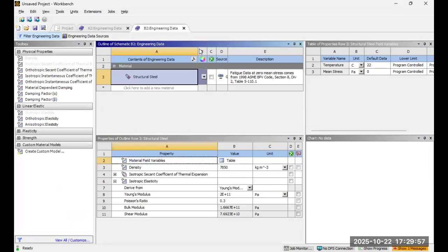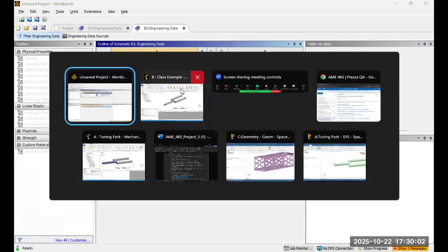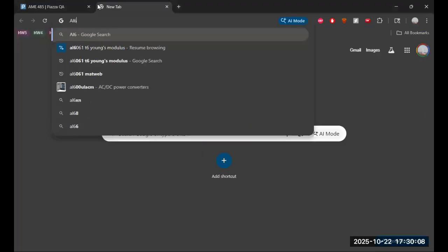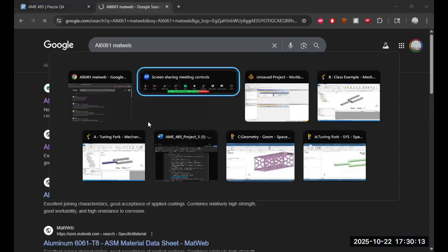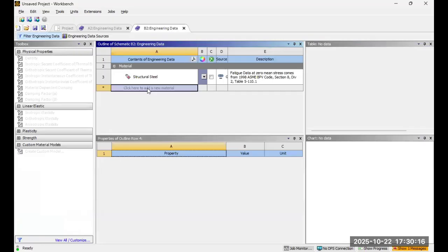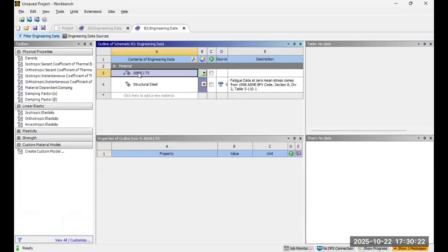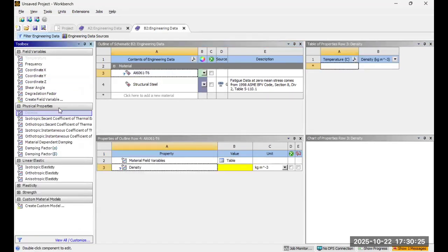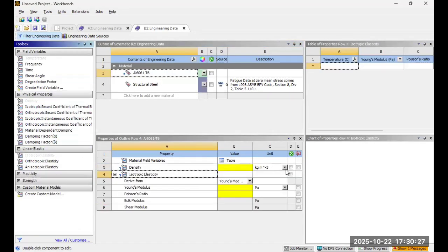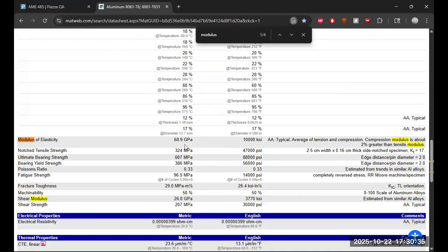So standard, we're starting off everything. This should be like bread and butter now. We'll make it out of 6061. So Al 6061, going to define the material properties. And so we always say, okay, make sure you're defining density. In modal analysis, it's especially important that you define density. If you don't define a density, you actually cannot run the sim. So we're just going to go ahead and define modulus 68.9.